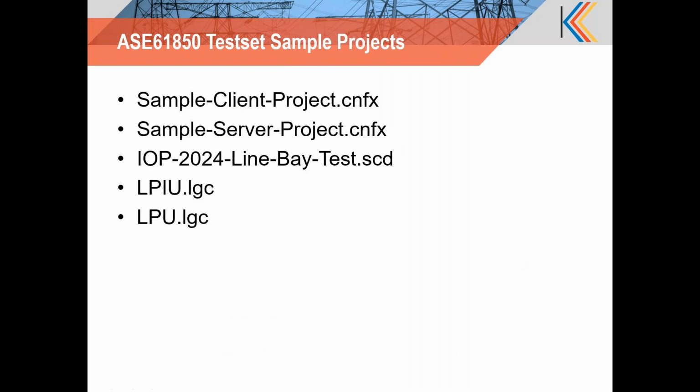You may load the client using the sample client project. You will be able to load the server capabilities, multiple IEDs, using the sample server project, and we have already installed this ICD file or SCD file, that line-based test file, as part of the installation.